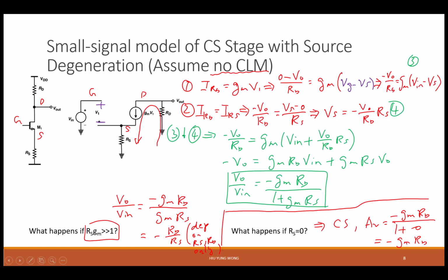And it makes sense because it needs to be the negative gain, right? Isn't that we just say that V in goes up, V out goes down? So the gain needs to be negative, just like common source, right? That's another way for me to check that if I'm doing it right or wrong, right? Compared to this, right? So yeah, we've done this, but so what? The point is we want to see if it makes sense with what we have learned.